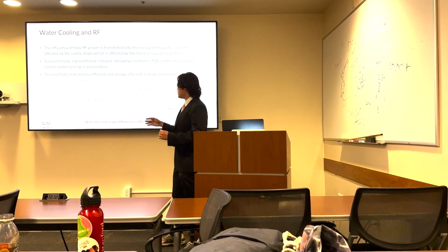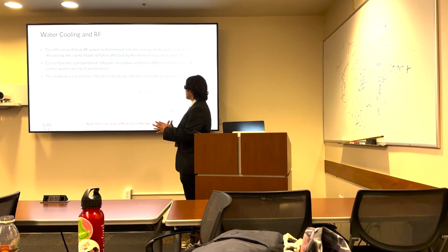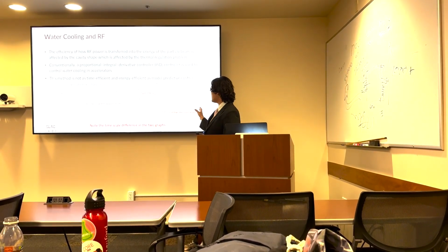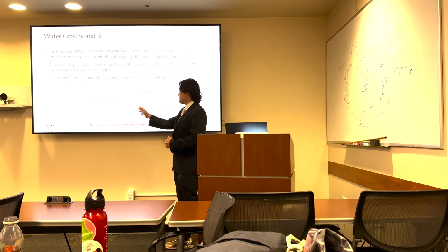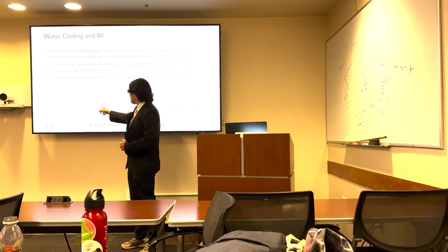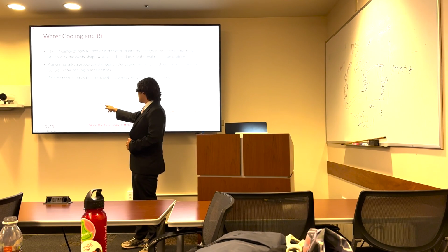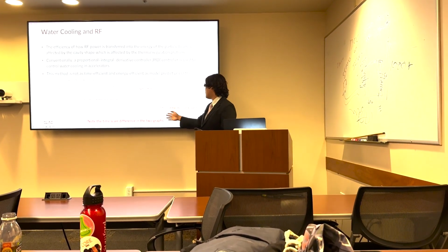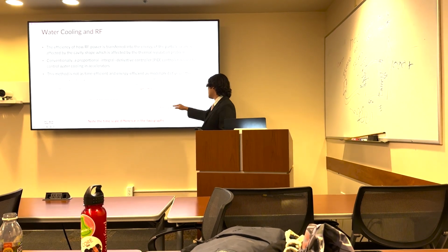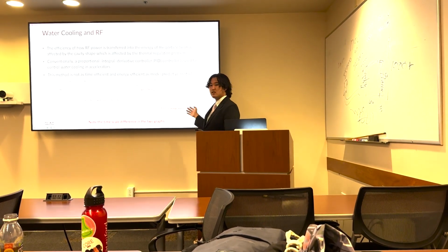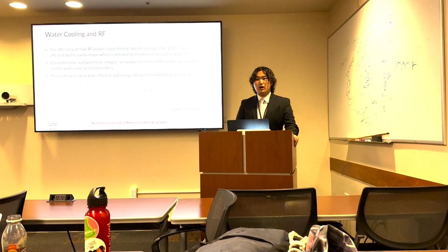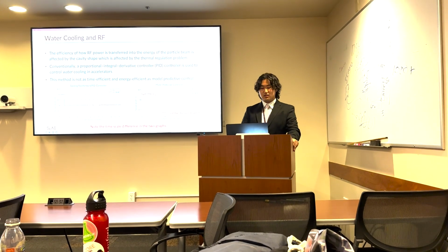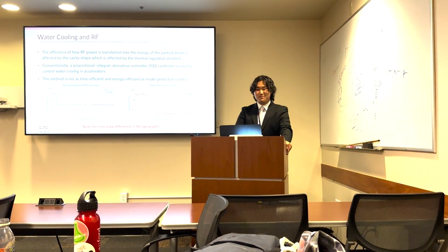So you can tell that compared to something called model predictive controller, which is something that we're using machine learning modeling, it's a lot less time efficient, where you're seeing it takes almost 5 times the amount of time in order to normalize at the target temperature, whereas model predictive controlling takes only about 5 minutes or 4 minutes to really start to get to the target temperature, right? So it turns out that it's a lot more time efficient, and for that reason, we are using machine learning modeling to try to tackle this problem.